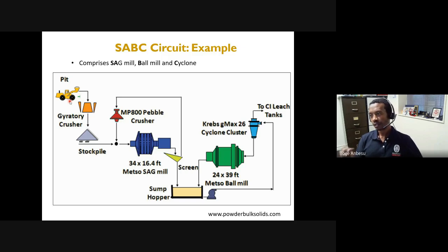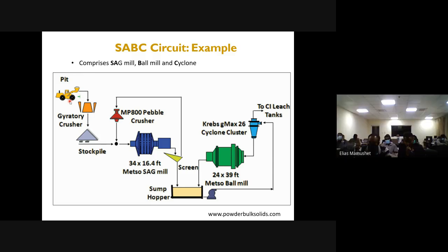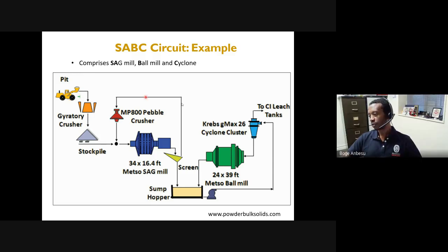If we send fine material to our primary crusher, the impact is that it will choke very quickly and it will reduce the capacity of the crusher significantly. So there's no point in feeding fine material to a primary crusher. So we need to remove that before we feed a primary crusher with large rocks, typically. Okay, so that's where screen can be used in a typical comminution circuit.